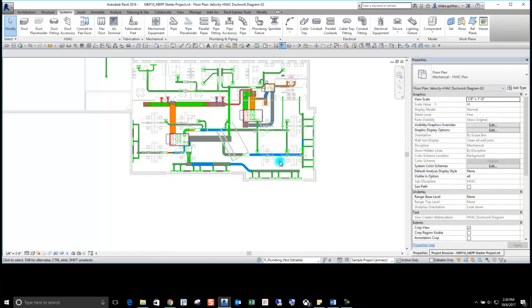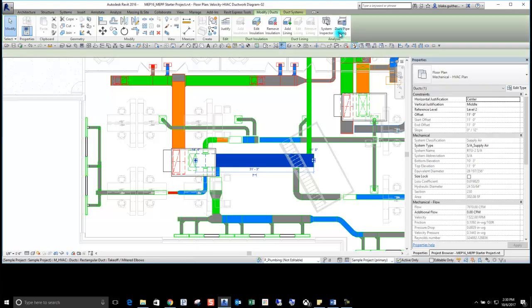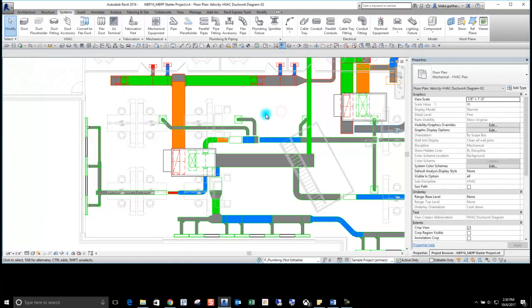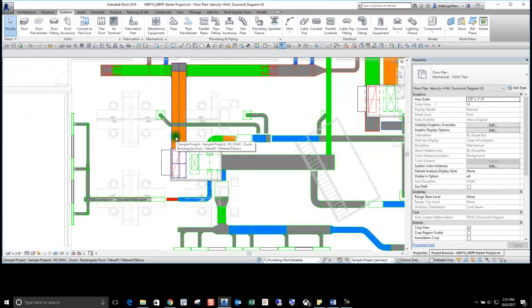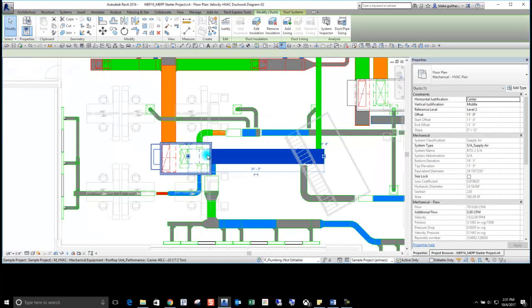And if you run your load calculations, it's very easy to determine what the block airflow is, and then you size your ductwork system off of that. So with using Revit's duct sizing tools, you just need to be aware of that. When you get to a section of duct that now contains all of the airflow, Revit's going to see the peak airflow, and if you're sizing off block airflow, you necessarily don't want to use this particular duct pipe sizing tool to size that. Like this return air duct was one of those situations. So it's just something to be aware of when you're using these duct sizing tools.